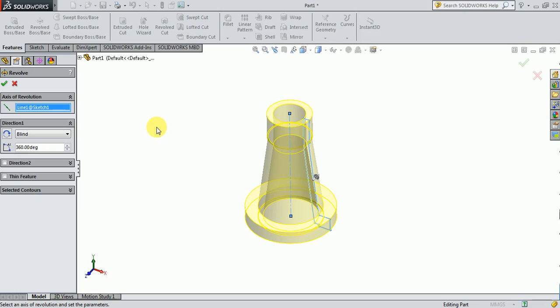Okay, so we created one sketch. Within the sketch we have to add the material, but how should the material be added? Material should not be added perpendicular to the sketch. Material should be added around an axis which has been defined now. So material should be added within that sketch, but around an axis. So that is what this revolve feature indicates. Then click on OK.